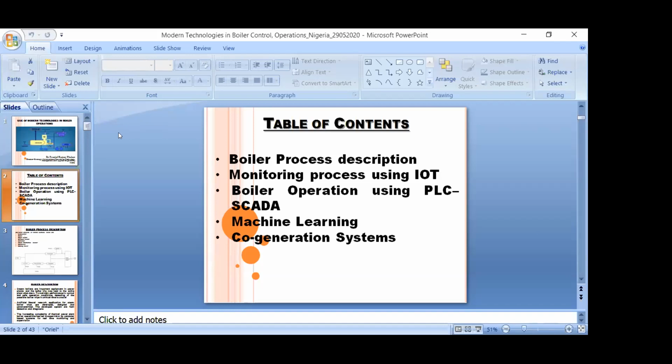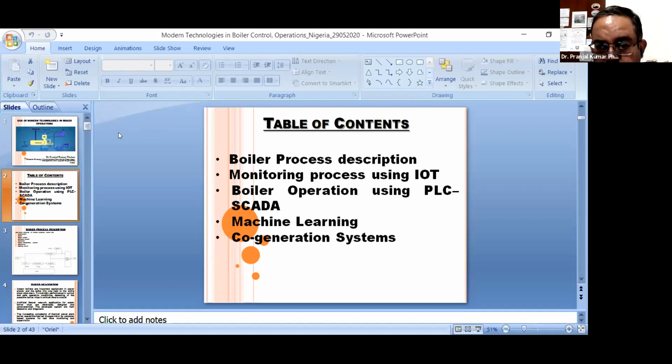And that's from Madaki. See, the water quality is basically based on the boiler feed water quality as per the international standards. So before setting up in the plant for boilers, the water quality is always checked before using it as feed water. The boiler feed water sensor will tell you beforehand that the quality of feed water is not as per the parameters. So obviously it will trigger information to all the concerned operators that you need to check the parameters, because these are the parameters which are required, but it's not coming at the level. So based on that, they can take up the case, and they can treat this water.